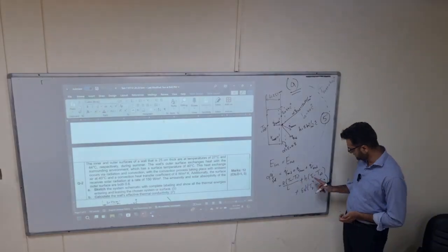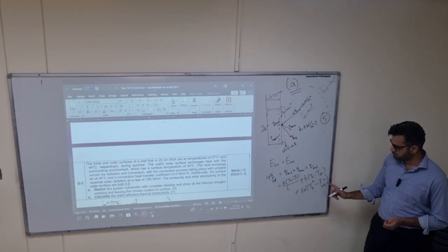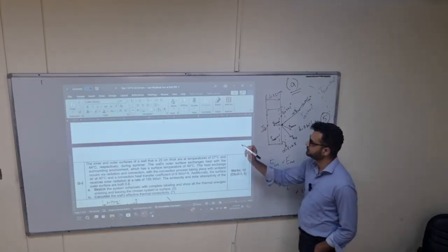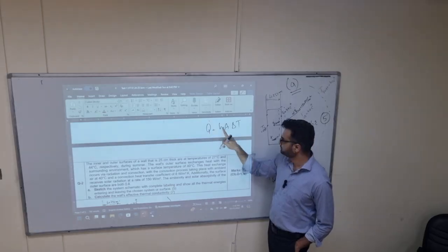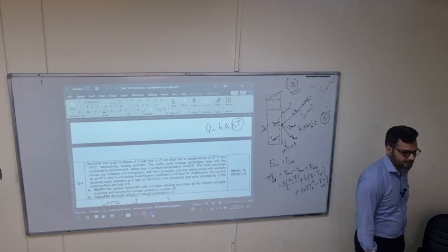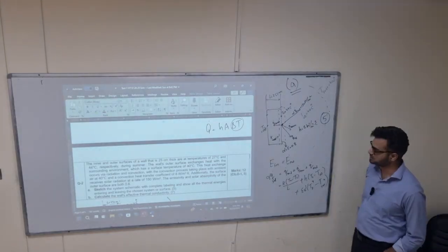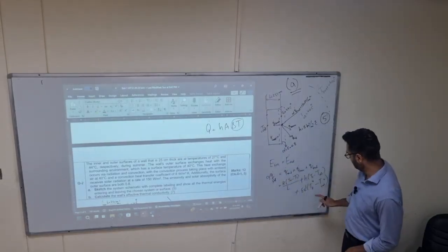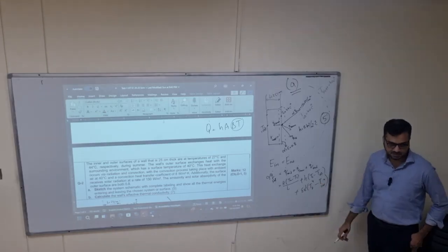Here we can use Celsius in both these terms. Watt per meter square Kelvin, no difference? No. Convection, because convection coefficient is h A delta T. From here, what are the units of h? Watts per meter square per, what is this thing? Delta T. So whether Celsius or Kelvin, it's same. So no need to change. It's already delta T. But here, both of these must be Kelvin.